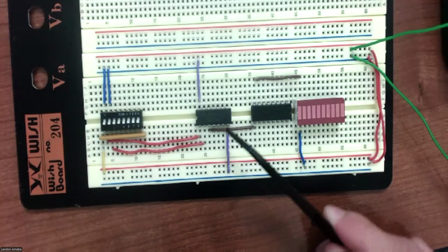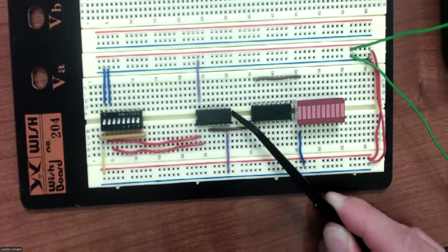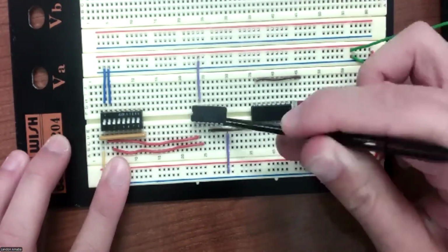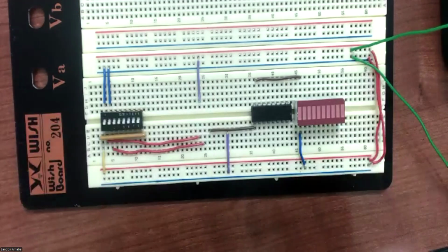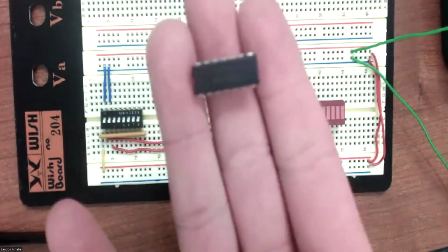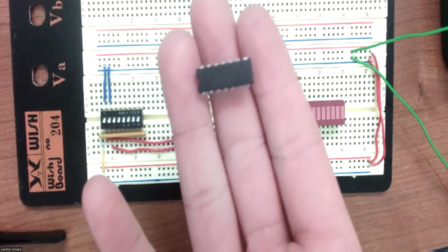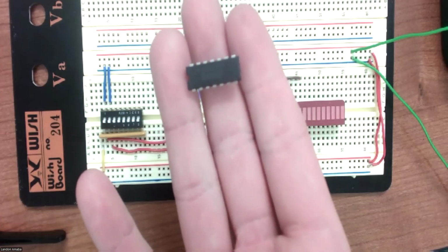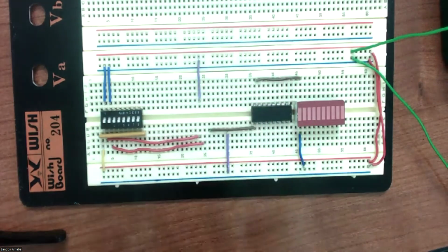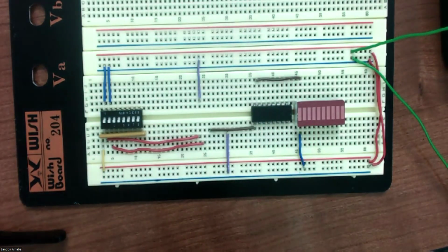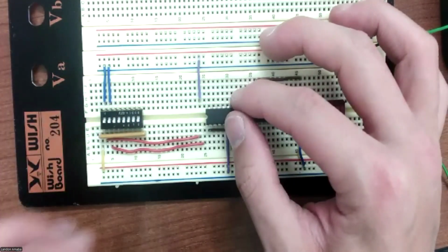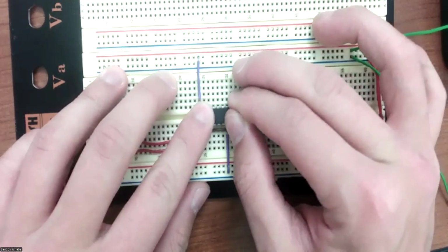Moving on to the next part of our circuit, this is going to be our chip. I'm going to remove the chip from the breadboard and show you a little bit of how this works. In this video, we're going to use a 7400 chip, which is otherwise known as a NAND chip. You're not able to see very clearly in the video, but if you examine the last 2 numbers, you'll be able to make an easy differentiation on what chip you have.